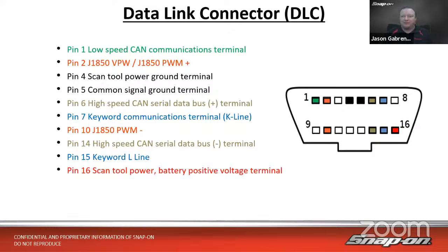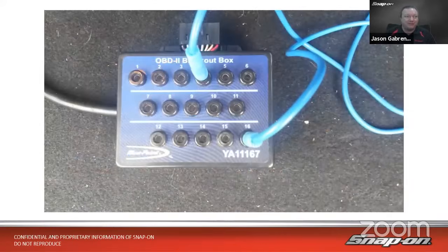So that's why we do these classes, right? Good way to get into the diagnostic connector as well, without damaging anything. So we don't want a front probe, because that could spread out the terminals. That would cause a communication problem, perhaps. It's usually pretty hard to back probe there, right? Because they're underneath the dash somewhere and pretty hard to get to normally.